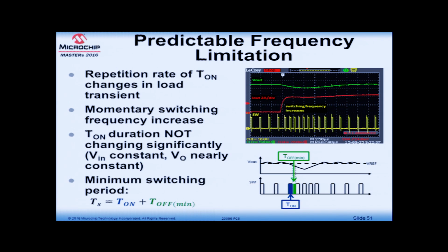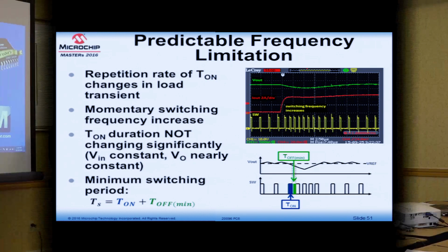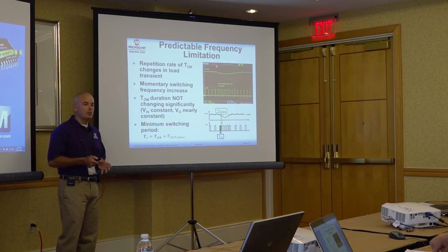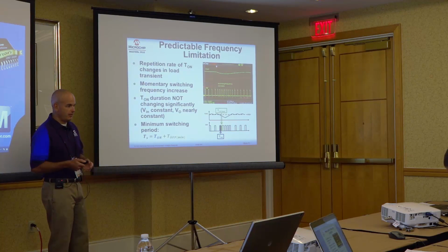So at the end, we can put a safe number on the minimum switching period. Even if the control is fully saturated, the minimum switching period will never be shorter than whatever T-on we have in this input-output voltage condition plus the minimum off time. So it is true that the frequency changes. It is also true that the frequency will not go crazy.